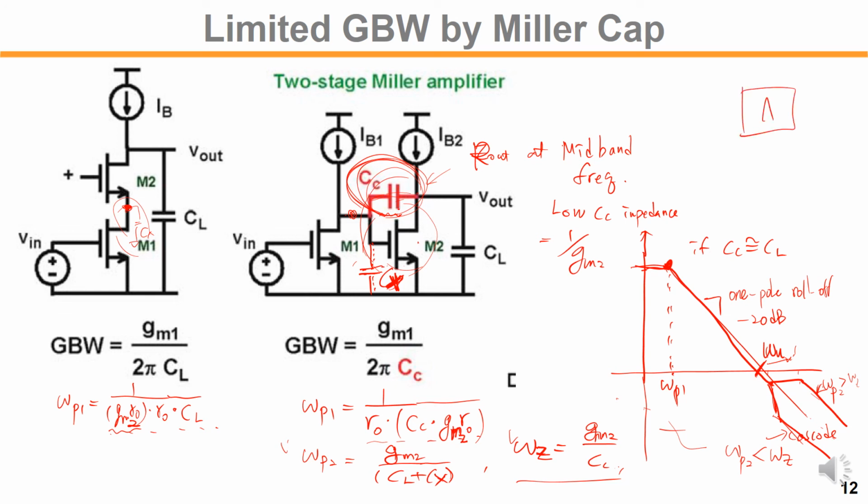So in a feedback system, let's say we have A and feedback factor beta, with plus and minus here. The phase shift from this point to when the signal comes back, if there is a 180-degree phase shift there, then the loop will be unstable.